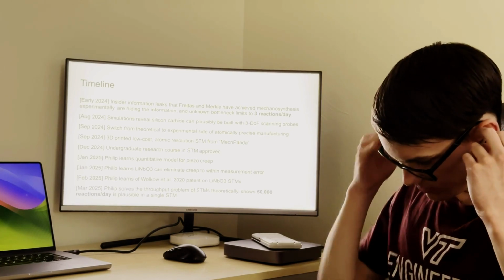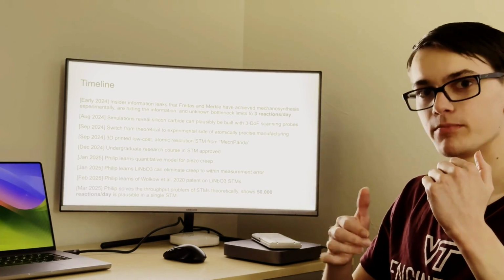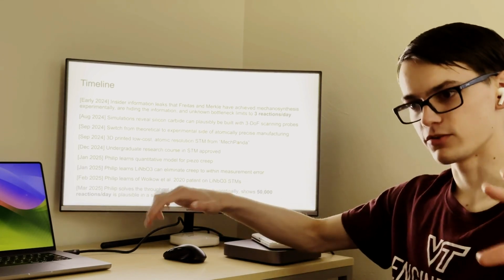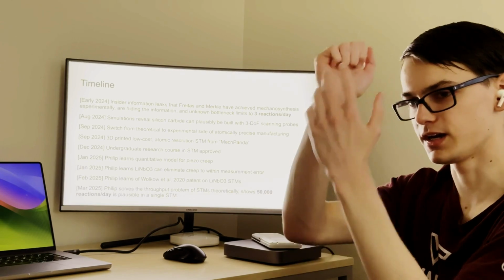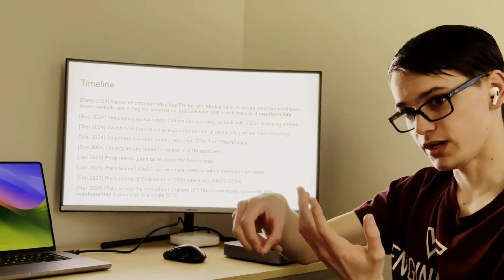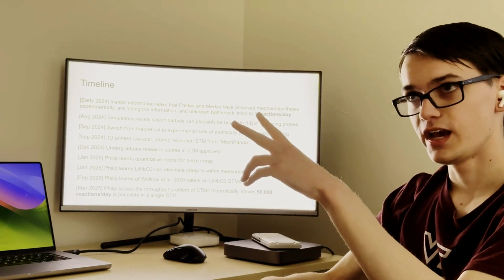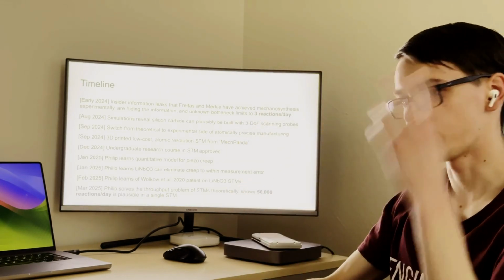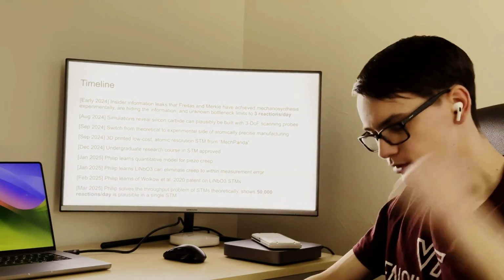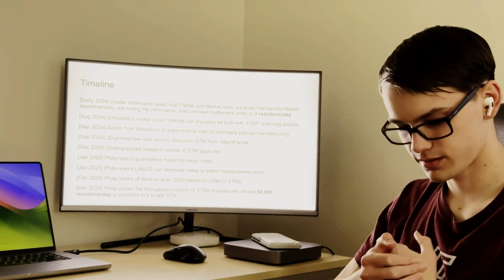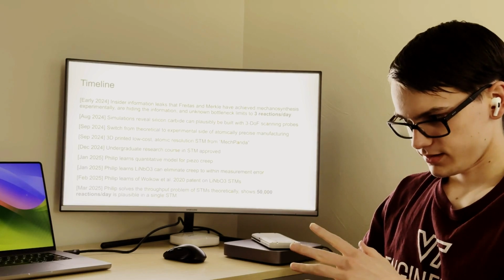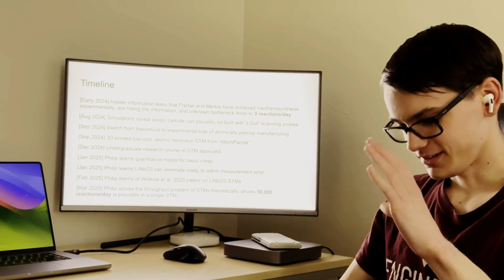So I tried a bit and I found that silicon carbide, specifically a certain orientation of a silicon 111 surface where the silicon to hydrogen bonds are what's pointing up, you can actually form a five-membered ring with a silicon to silicon bond. And I spent about a week making sure that that reaction works every time, and I could be extremely confident that it's physically possible to make that. And that five-membered ring did form with a silicon to silicon bond.